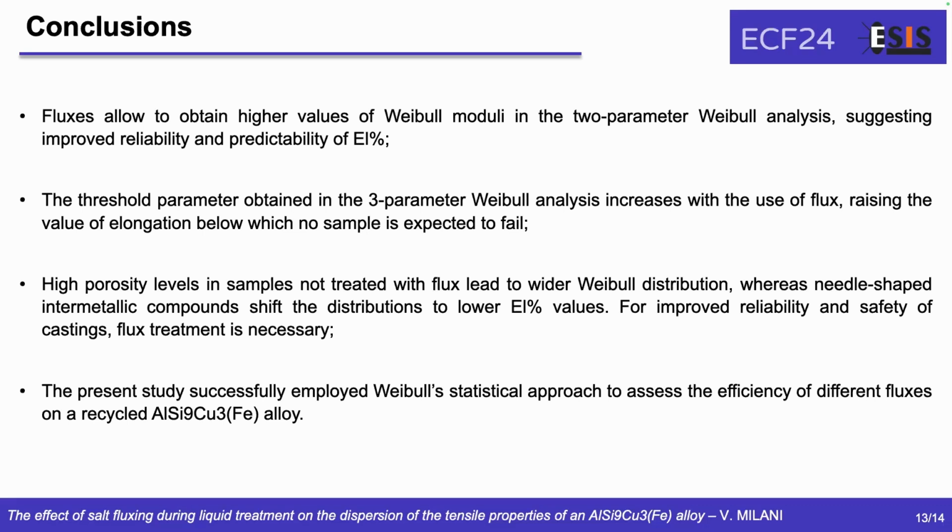Then, high porosity levels in samples not treated with flux led to wider Weibull distribution, whereas the needle-shaped intermetallic compounds shift the distribution towards lower elongation values. So for improved reliability and safety of the castings, flux treatment is necessary, as well as temperature control. And to conclude, the present study successfully employed the Weibull statistical analysis approach to assess the efficiency of using different fluxes on a recycled aluminum silicon 9 copper 3 iron alloy.